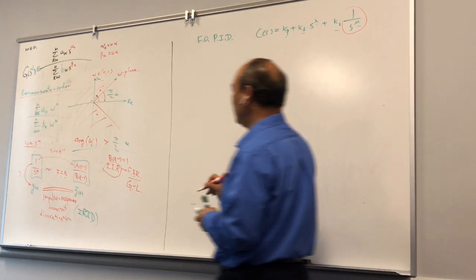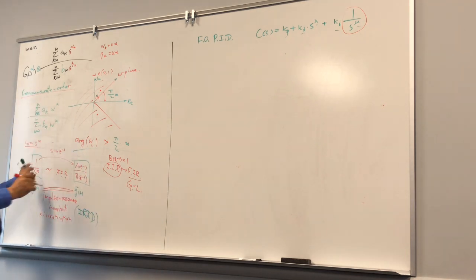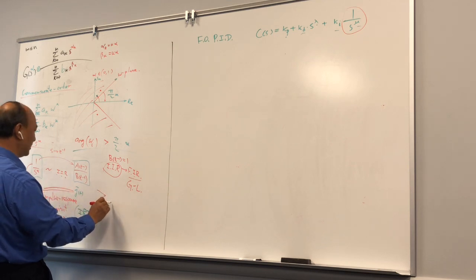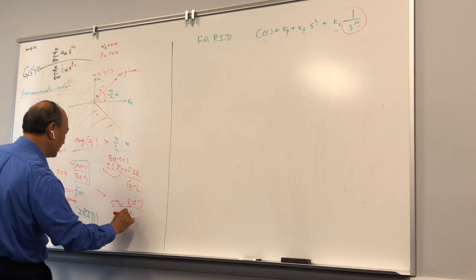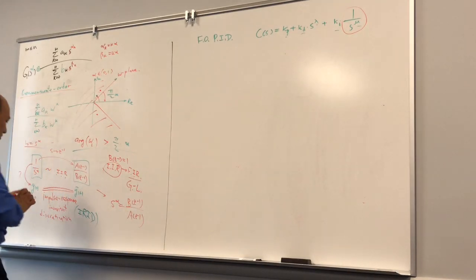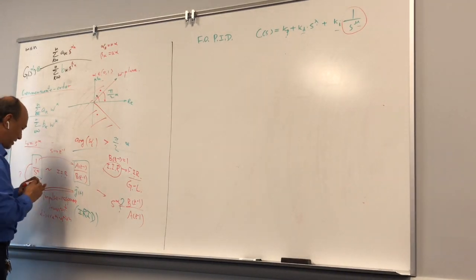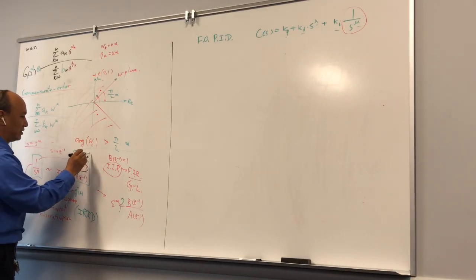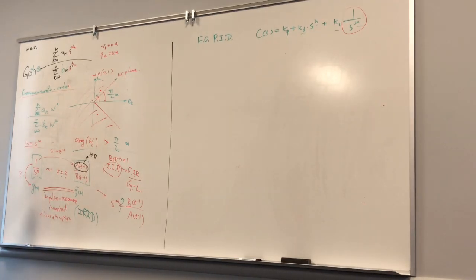But remember, you want to have A(z), B(z). Can you say that s to the power of alpha is B(z) minus 1 divided by A(z) minus 1? Can you simply do that? Be careful, probably not. Because this must be minimum phase, meaning there are no zeros outside the unit circle.